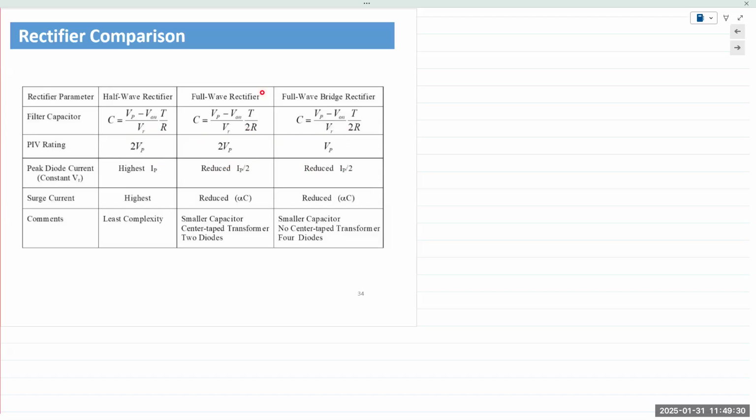The question being asked is, doesn't it depend on the source of the input voltage? The answer is yes. If you use a transformer, the input to the transformer is not the input to the diode circuit. The output of the transformer is the input to the circuit. So when we state Vp, we are referring to the input to the diode circuit, not the input to the transformer.